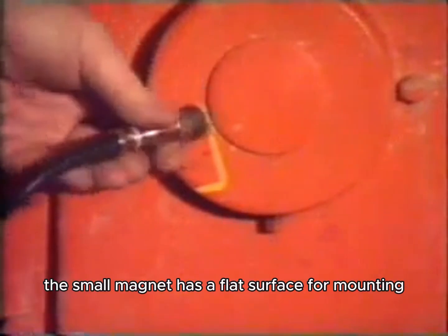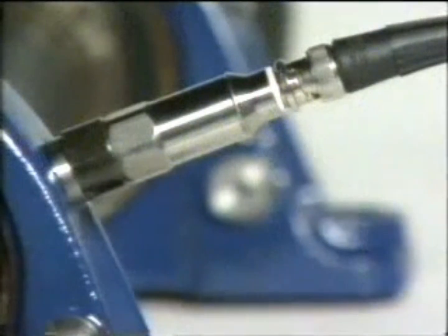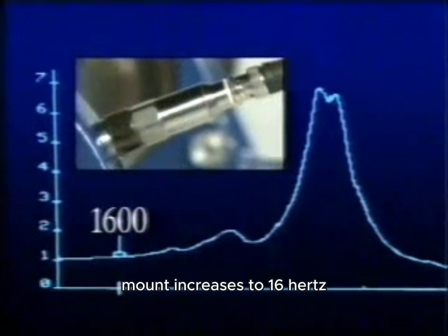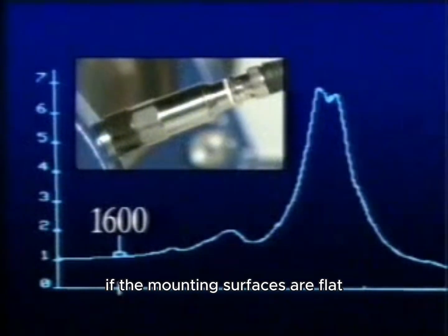This small magnet has a flat surface for mounting. To avoid erroneous data due to unstable mounting, it should be used only on flat surfaces. The linear range of the same sensor with this magnet mount increases to 1600 Hertz and makes it even more desirable if the mounting surfaces are flat.